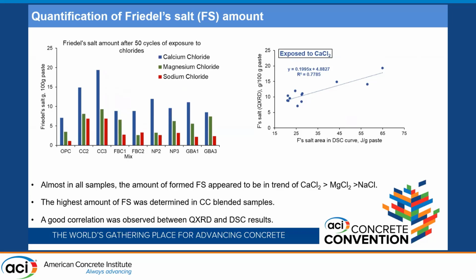Also, we tried to see how the area under the curve in the range of the Friedel salt decomposition in the DSC curve can agree with the Friedel salt amount quantified by QXRD. Here you can see that the correlation is pretty good.